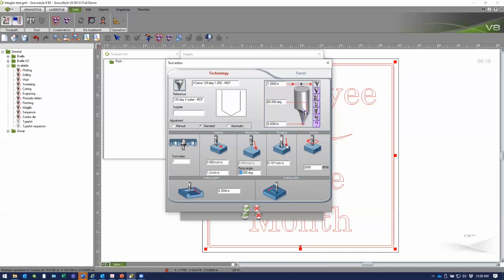And what would happen is something would have to give. If it impacts and feeds so fast that the cutter can't remove the material to clear its path, then it's going to fracture the tip of the cutter, or it's going to hang on the material and move your material or stall the machine. So it's important to match your plunge rate, and there's a bit of trial and error. Again, start slow and then increase this until you find a feed rate that's comfortable. And typically your ears will tell you when the machine's struggling, or the quality of the cut will tell you when the machine's struggling and you're feeding it too fast.